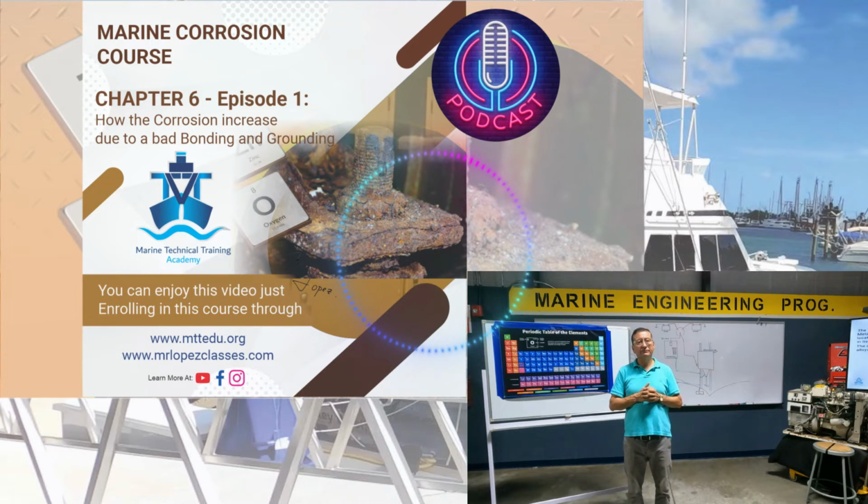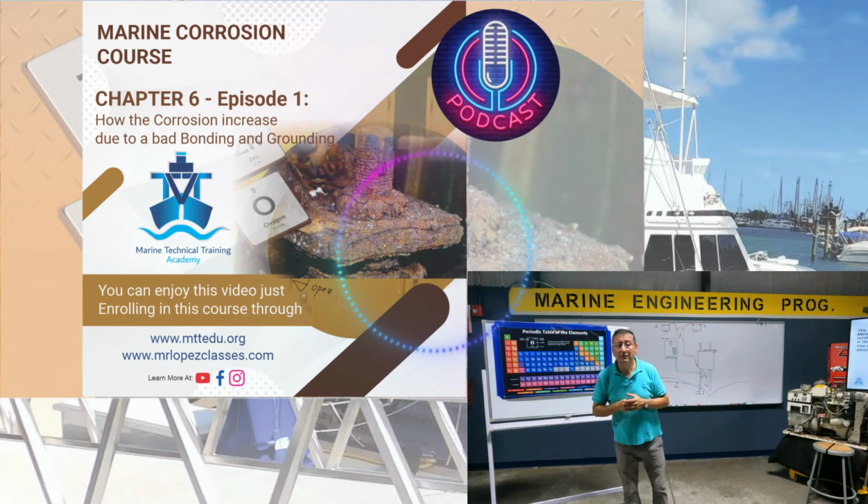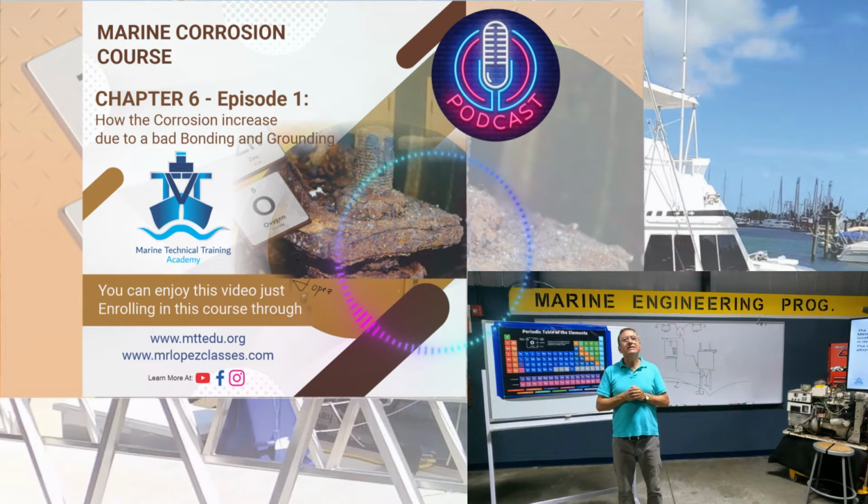95% or more of the problems in a boat are electrical problems. The majority of the problems in a boat end up being an electrical problem. And 95% of the electrical problems are related to a bad ground, or loose ground, or corroded ground, or bad terminals, or improperly wired ground.